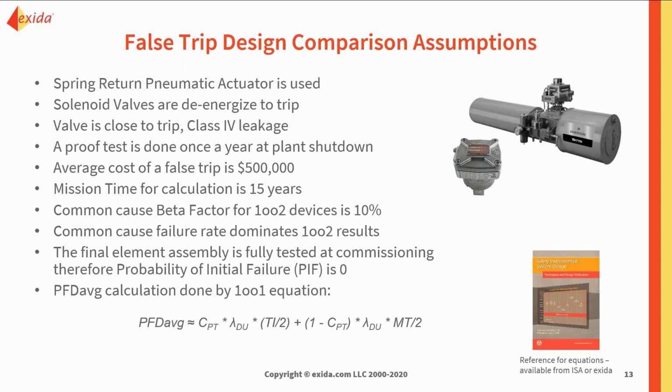This is one of those key main factors that the standard talks about, that you calculate to figure out your SIL level. If you've done this PFD average calculation before, you know it's not just a simple little calculation, but there are a lot of things to consider, including 9 key variables. And with some of those variables, we had to make some assumptions for today's calculation.